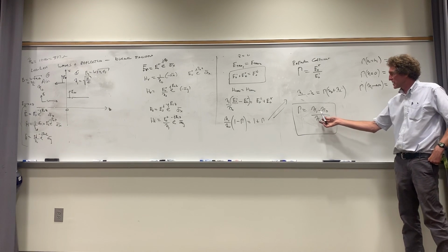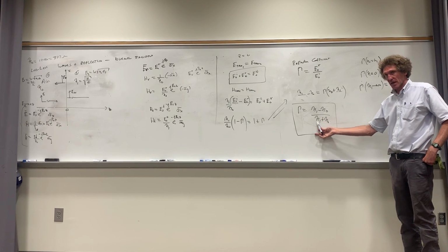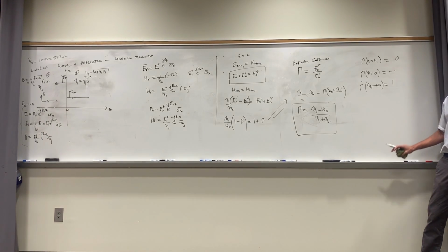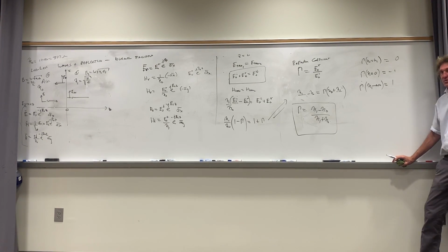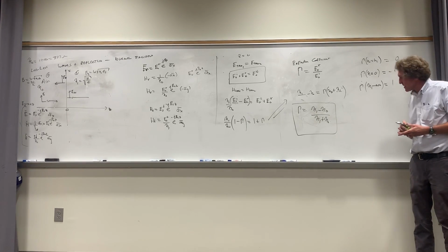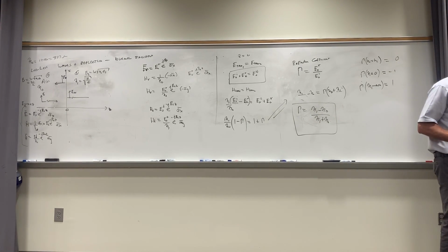Look, if it goes to infinity, it's really this divided by A to 1, and A to 1 over A to 1 is 1, right? And those are like open circuit, short circuit, match circuit. Back in the day when you did T-lines, remember? You had an open circuit, the reflection coefficient is 1. A short circuit, the reflection coefficient was minus 1. And a match circuit, the reflection coefficient was 0, right? So those are the three cases. And they're pretty obvious. And that's really it in a nutshell.